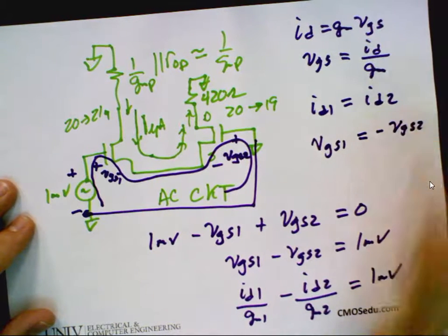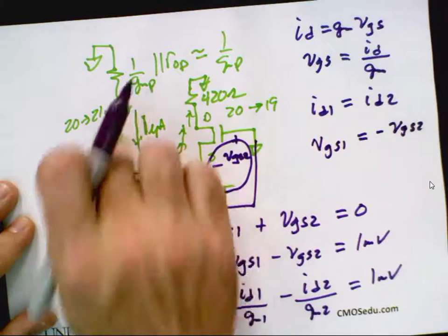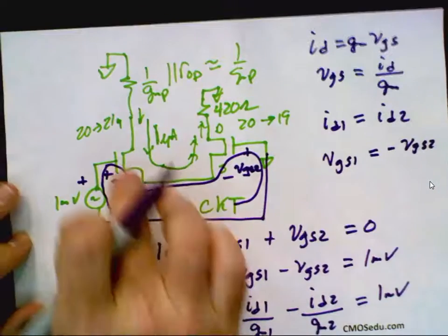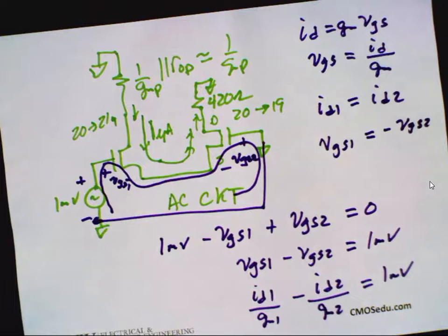Does anybody not agree with that? If I have an equal current flowing in each of these that's equal and opposite, and let's pause and make sure we understand that, then the VGSs have to be the same. Thinking of my yard example, if I turn my knob a little bit and a little bit of water changes in it, the other one I have to turn the opposite way to absorb that extra water so the overall amount going down is constant. So those VGSs have to be equal and opposite. Turn one on more, turn the other less. Any questions?